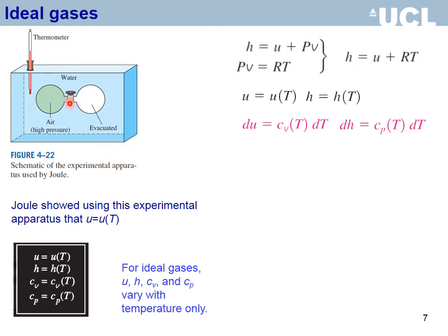Now if you think about it, what is the system we are analyzing? We are analyzing air at moderate pressures, as I told you. So this is a good approximation of internal energy. Now if you consider this whole container as your system, there is no work going in, no heat going in, and no heat or energy going out.